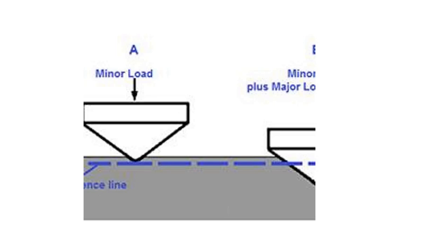A specimen is there, a minor load is applied on this indenter, then a gradually increasing major load is applied. So a small indentation will be there on that work specimen, and through that, by calculating diameter, we are calculating the Brinell hardness number. By calculating depth, we are calculating the Rockwell hardness number.